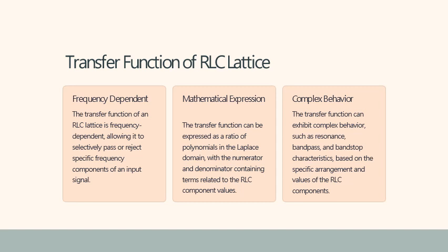of an input signal. Coming to the second one, mathematical expressions, the transfer function can be expressed as a ratio of polynomials in the Laplace domain, with the numerator and denominator containing terms related to RLC component values.